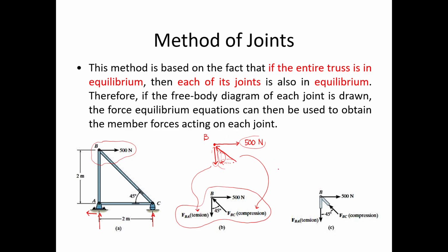All right, so this is how it looks if you draw the truss itself, with the internal force just inside the member. Of course, you can just draw the FBD and avoid drawing the truss. This one is just for further understanding that the forces FBA and FBC are internal forces. That's why we draw the truss or the member here.